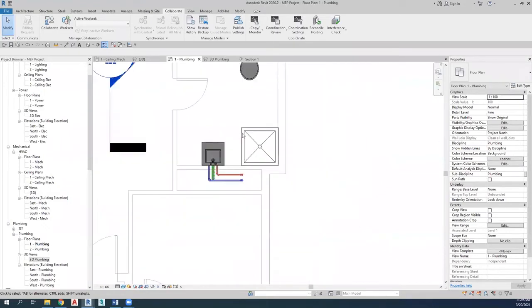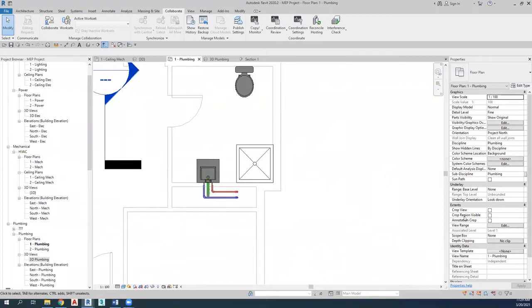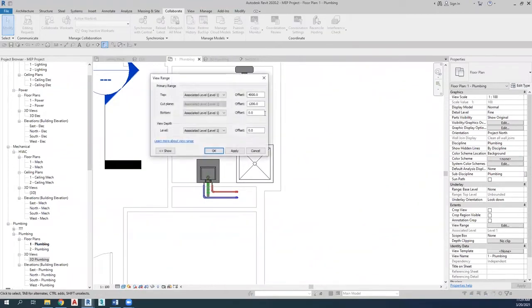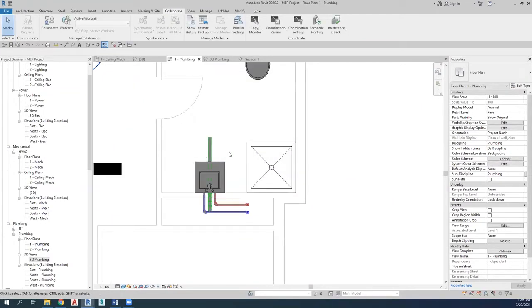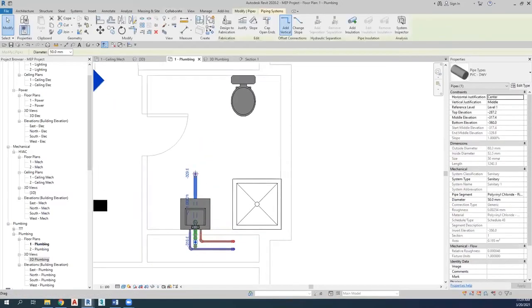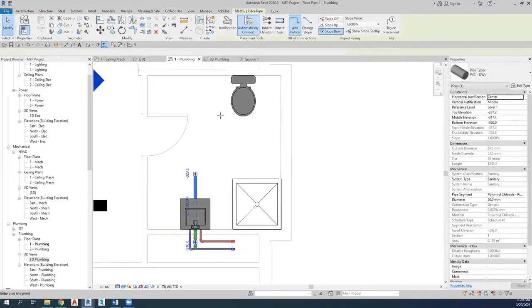We are drawing another pipe at a 45-degree angle, and we will lead it outside of the building. As can be seen, the 1% slope is also visible here. We set the size of the main pipe to 100. We are going to now be connecting the water closet to this pipe.